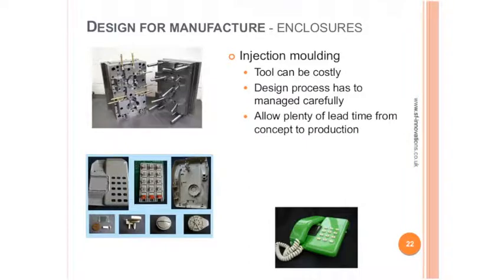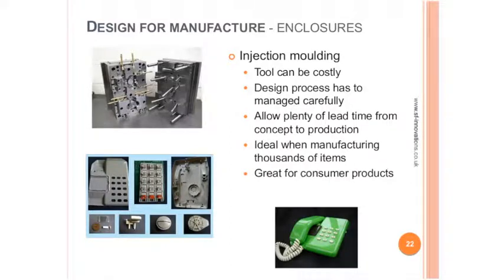And also lead time for injection molded parts can be high compared to other methods. It's ideal when manufacturing thousands of items, and certainly tens of thousands of items, and great for consumer products because the look and feel is good, and low cost of parts. So complicated, complex, but pays dividends in terms of a nice look and low cost.